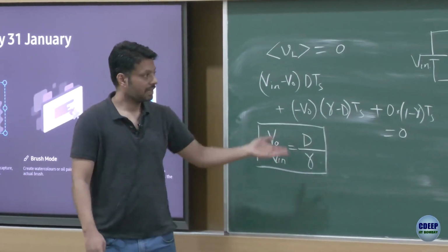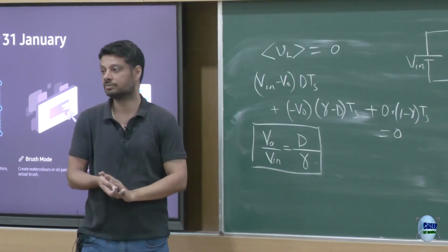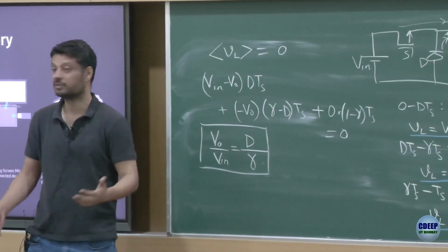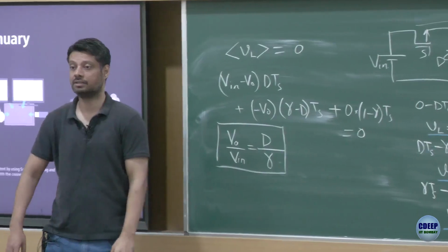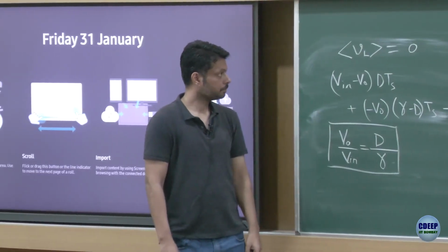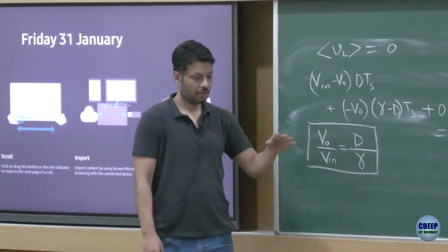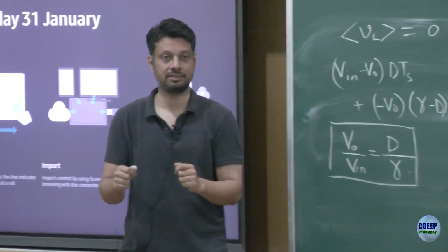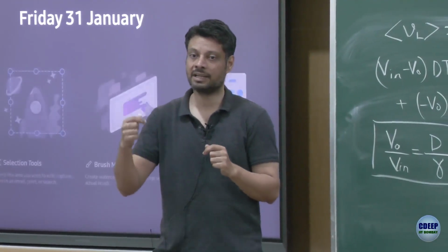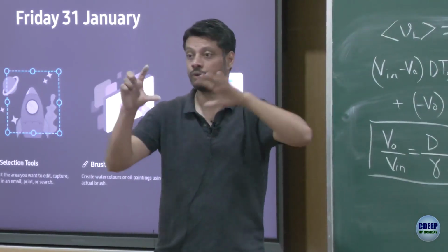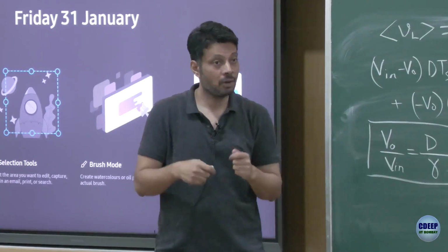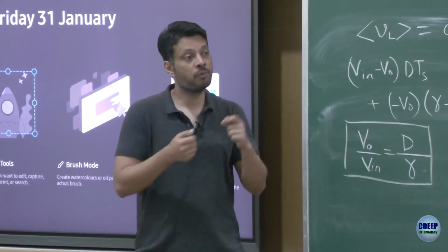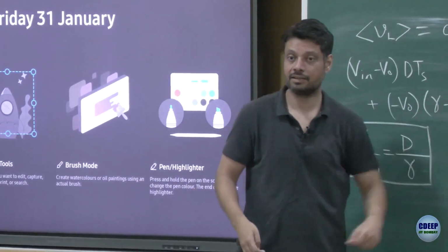And now with this expression you can think a lot, right? You can think about the output voltage average value, you can start thinking about the slopes of the lines that we have drawn. Now assume that a converter was operating, and I have slowly started increasing the load resistance. I increased it a little bit, I moved from the earlier case 1 to case 2, the output voltage remained the same. But now I further increase the load resistance, that means reduce the load current. Then I move from 2 to 3, this is the 3 waveform.